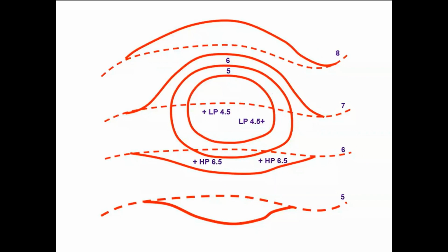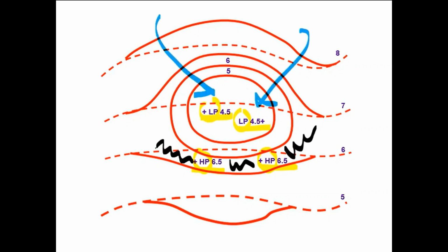So now we have added the high points and the low points. And yes, you must actually label them with an HP for the high point and an LP for the low point. What we've done with these high points is we have basically created a berm here along the downhill side of the system. So again, water is going to flow in to the system.